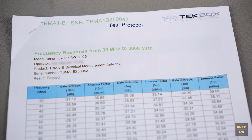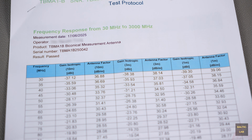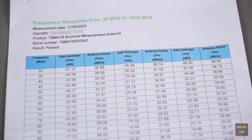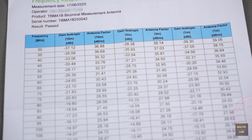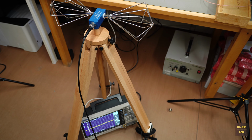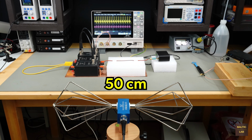This antenna provides well-defined antenna factors between 30 MHz and 3 GHz, allowing for accurate field strength measurements of radiated emissions. Although the improvised setup limits absolute accuracy, it remains suitable for relative comparisons between common mode and differential mode signals. The antenna is positioned 50 cm from the two-conductor cable.